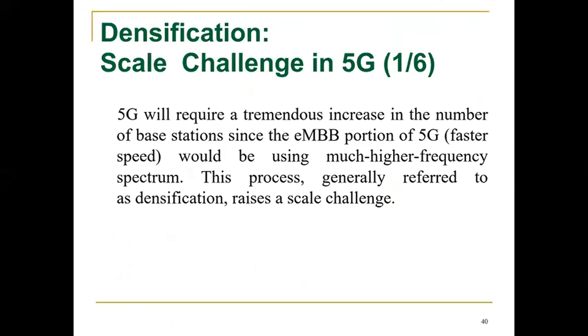If we reduce the size of the cell, we need to have more towers. But it's not easy to increase the number of towers in the city because of a number of reasons, environmental as well as some financial reasons. So that increase in the number of sites is a challenge, and this increase in the number of base station towers is called densification. Densification means in 5G you need more connectivity antennas available in your city at almost each corner of the city.